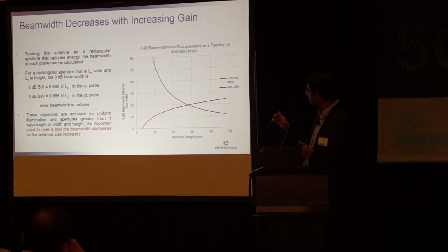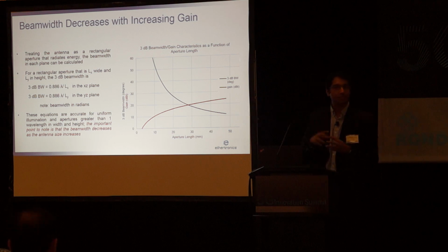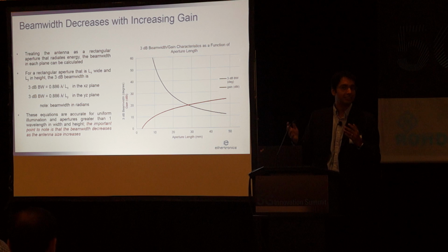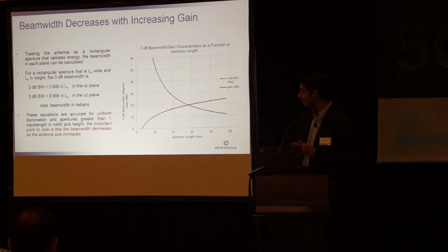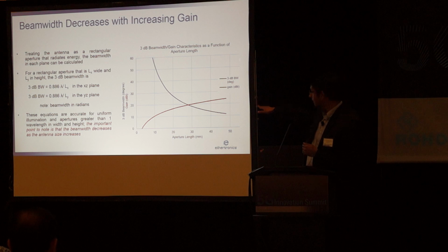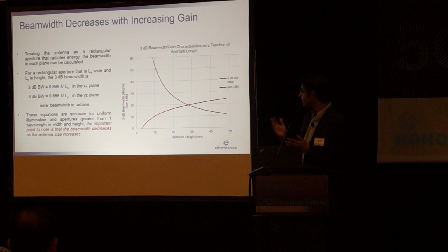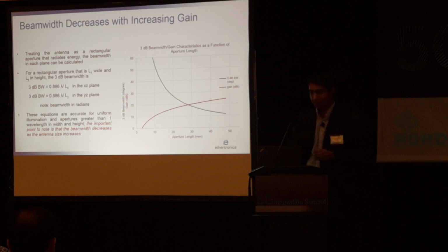Now as we start pumping up the gain, similar to what we saw from the earlier phase transmission formula and other examples at 28 gigahertz, if we are looking at 20 dB, 23 dB or even higher peak gains, the 3 dB beamwidth is going to become very, very narrow. And you see the threshold, the intersection point, right now is where the beamwidth is under 20 dB in the teens, and it just continues to drop eventually till you are down to maybe a 3 dBi beam.